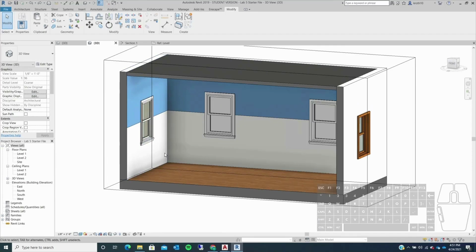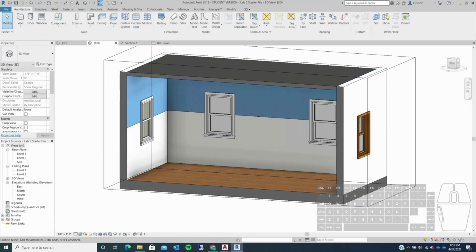Now we're actually going to create the trim. All right, so to do that, we're gonna use maybe a new tool, another new tool, hopefully, that you've maybe not seen before and you can get some practice with. If you go here to wall, in the past, pretty much all you've probably been doing is just clicking on the picture of the wall. But if you actually click the drop down, you're gonna get some more tools here. So what we want is this one called wall sweep.